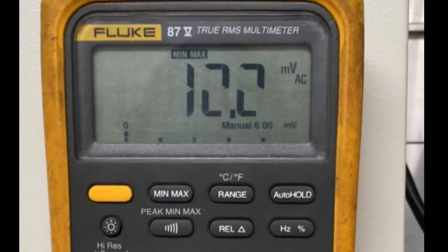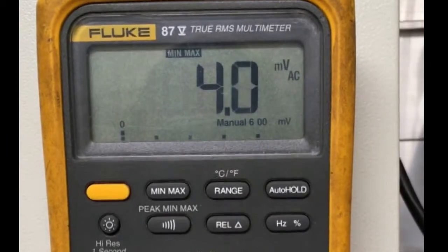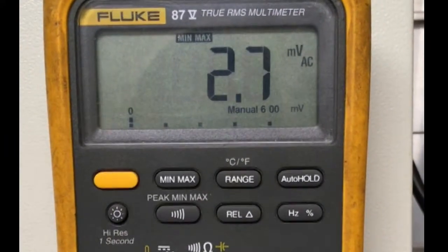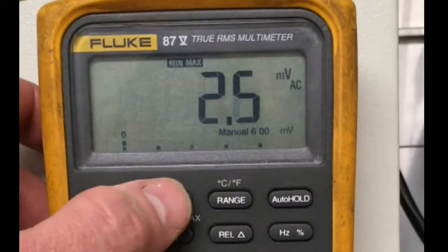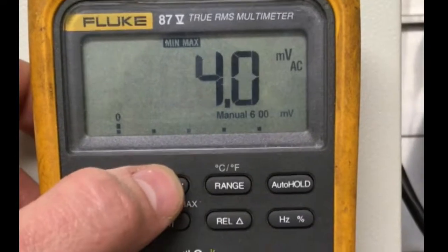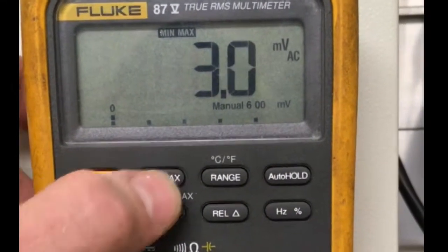The min-max button can be selected at any dial selection. Once selected, the meter will begin recording the lowest and highest values recorded. Each time a new minimum or maximum value is recorded, the meter will produce an audible tone. Once you have entered this mode, the screen will show the current measurement, but you can toggle the display to show maximum, minimum, and average values.